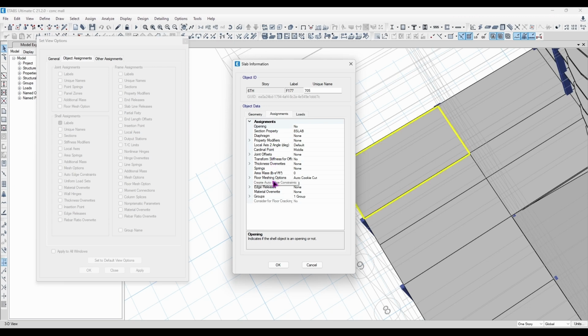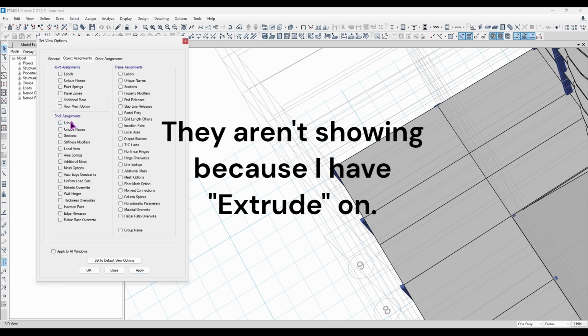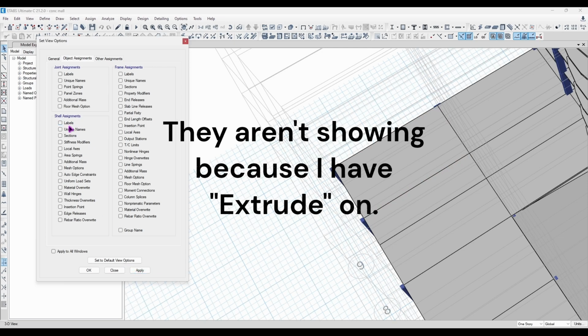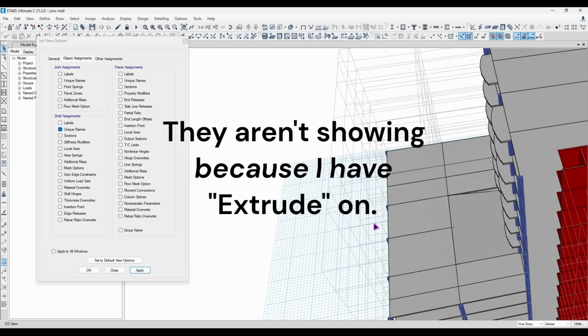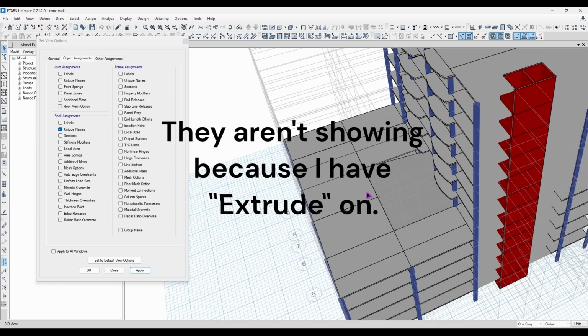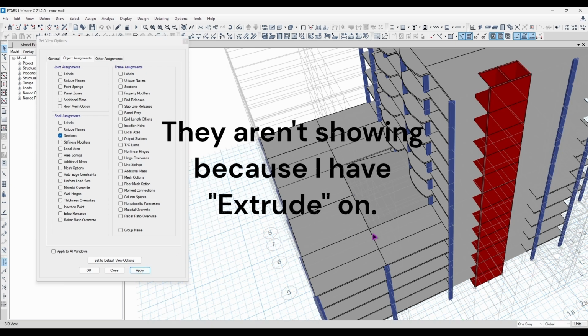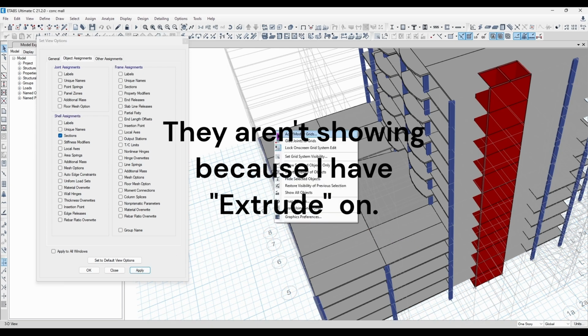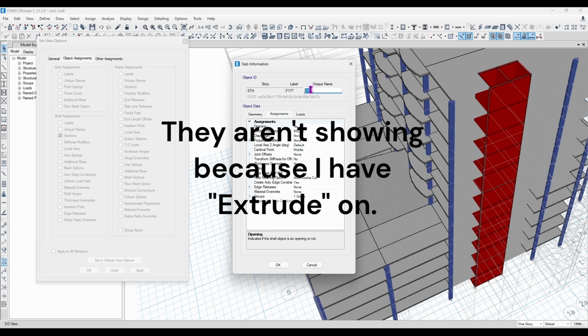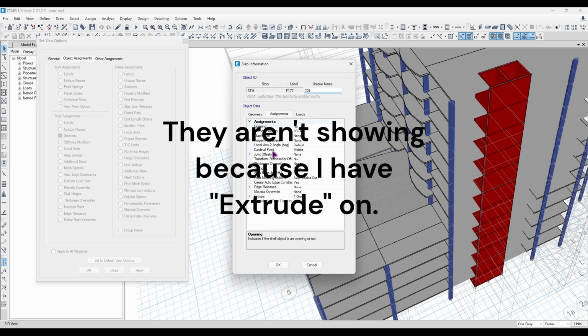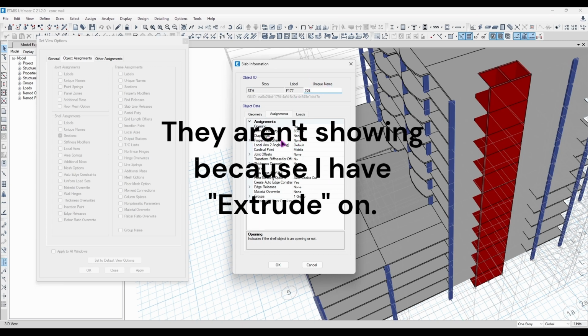Its label you can find somewhere here. Oh my bad, there it is. This is their label, so it's F17, F177. So this is technically what a label is. Unique names is just the definitions of the slabs. It might look a little tiny, so we can tweak that from the option settings later on. The sections, the cross section of each slab. If you can get on here, you can just get everything you need. From here, that's the unique name, the label, the cross-section property, the diaphragm, property modifiers, and so forth.